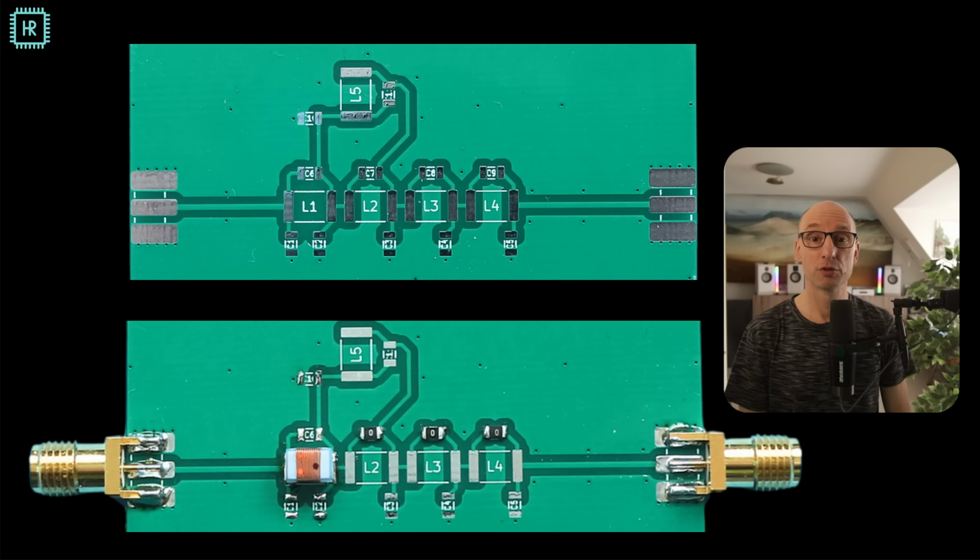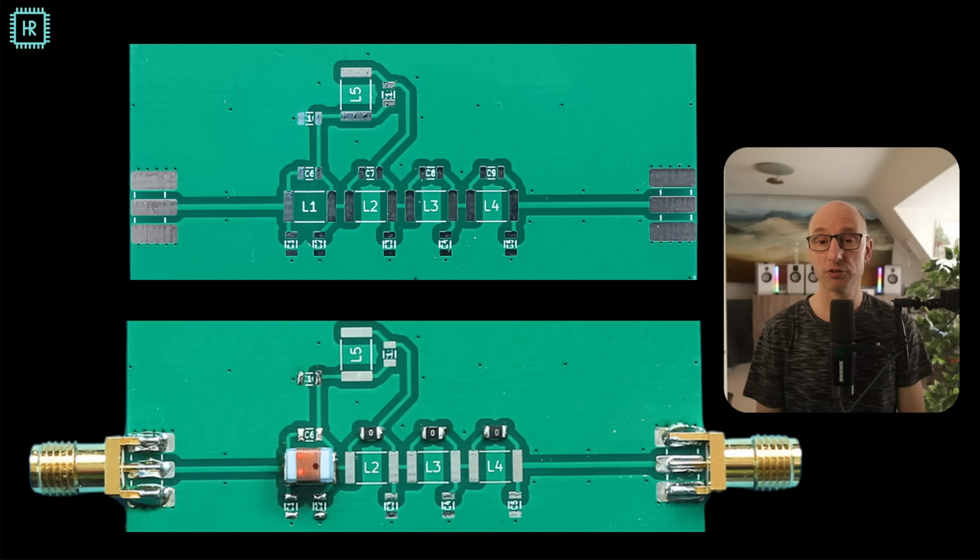What you would normally do is modify the actual board you have by drilling extra vias, rotating components, etc. But a dedicated board is more reproducible for demonstration purposes like this. The upper picture shows the board without components. The lower picture shows the starting point for debugging. Only a single inductor is placed and the rest of the filter is shorted using 0 ohm resistors.